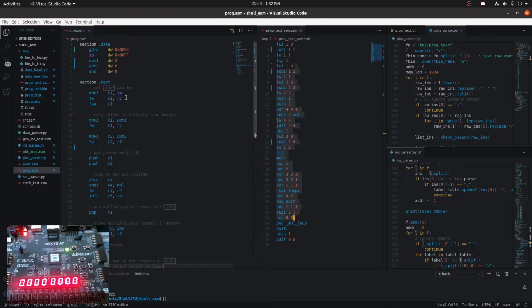So anyways, you can see we got a data section and a text section. Data section is going to get loaded into data memory, and the text section gets loaded into instruction memory. And this CPU is a hybrid architecture, so those are two distinct block RAMs. So the first thing the program does, initializes the stack pointer. CPU has a hardware stack, so that's nice.